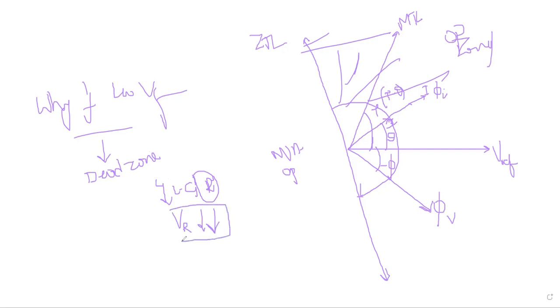So you are not able to do the operation of this directional overcurrent relay because of the voltage collapse. And if the fault occurred more close to the potential transformer, the voltage will collapse, so the directional overcurrent relay will not detect because of no voltage signal. So that is the reason.